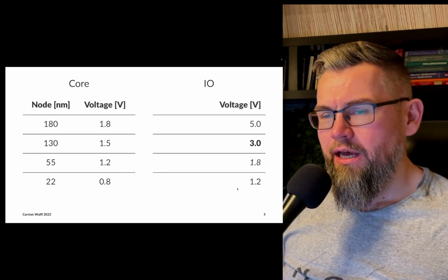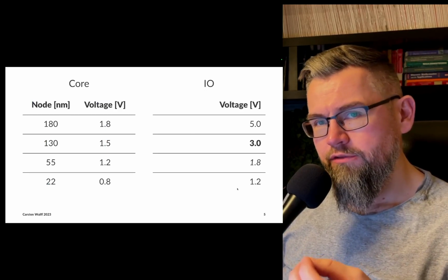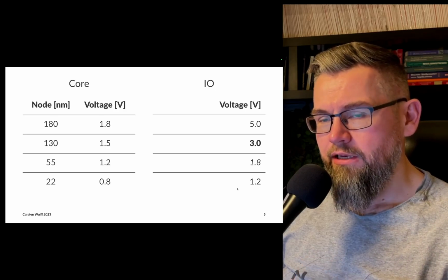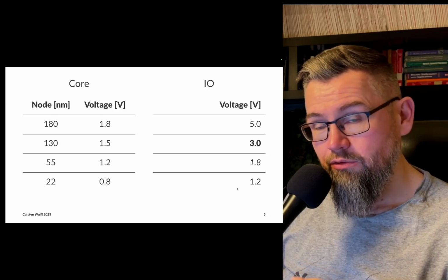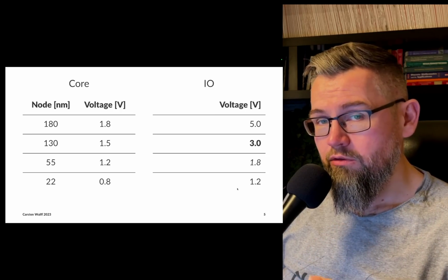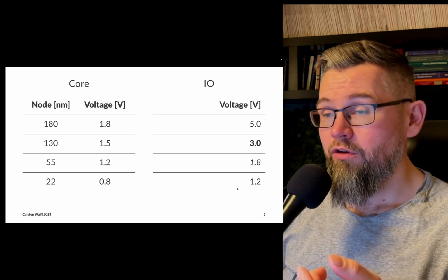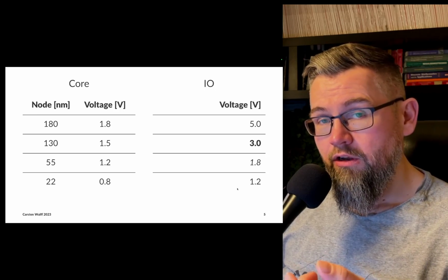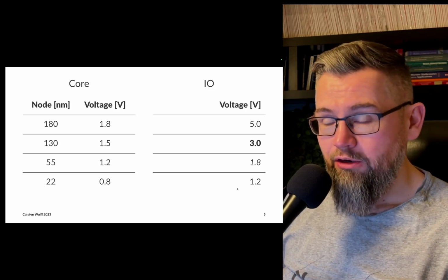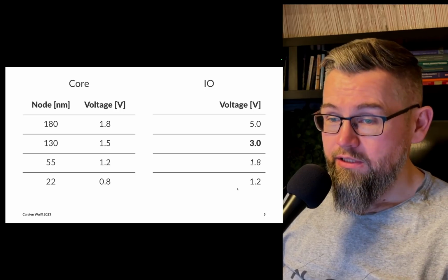Now, when we look at integrated circuits, how much voltage the gate oxide can survive is simply a function of distance and the type of material. Now, in 22 nanometers, for example, a quite common voltage is 0.8 volts. If you put more voltage than that on your gate oxide, then your lifetime reduces. Now, back in 180 nanometer, the voltage was 1.8 volts. And it was easier.